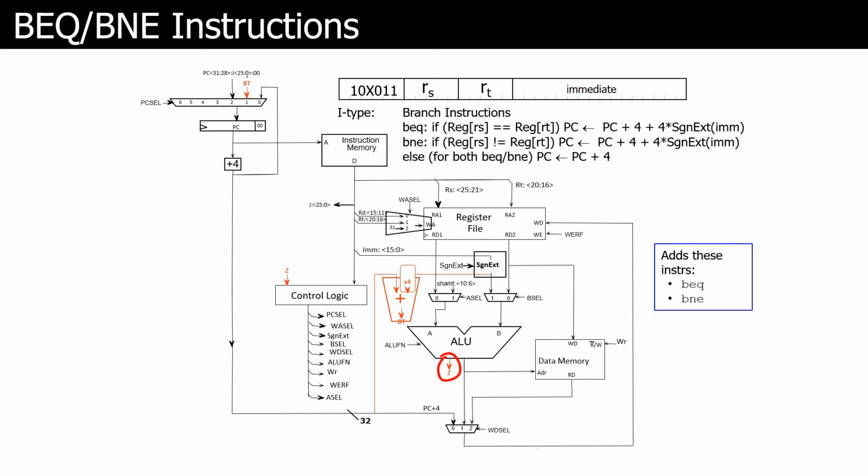So what we have here is branch targets coming up here. First of all, it'll look at the current PC value, and it'll send it in here, and it'll also look at whatever value you sent into the immediate, and it'll come in here. It looks like what happens is it'll then see whether Z is set to 0 or not, and based on that you have your two branch target outcomes, and that'll go into your PC select, and if you select 1 for PC select, it'll become your new PC value.